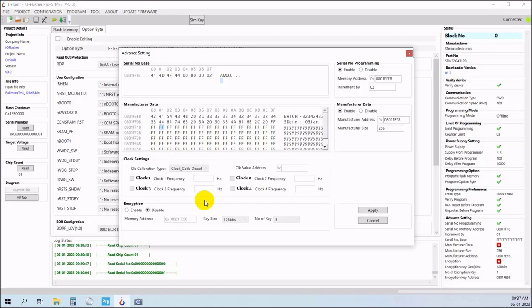server. So how will it happen? During the provisioning, during the first production provisioning, I should say, your device will send any or all of these keys to the server by encrypting them with the known key, so that the server can decrypt those keys and save them for further use. And once your product is in the field, nobody will be able to know the keys which are dynamically generated and stored in the device. So only your server knows about those keys.